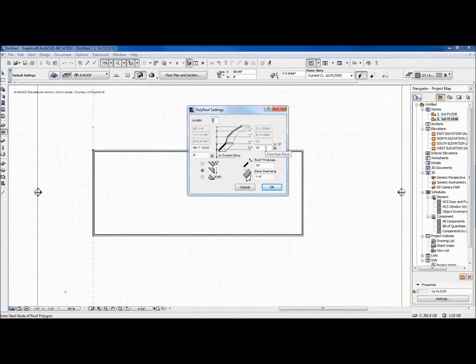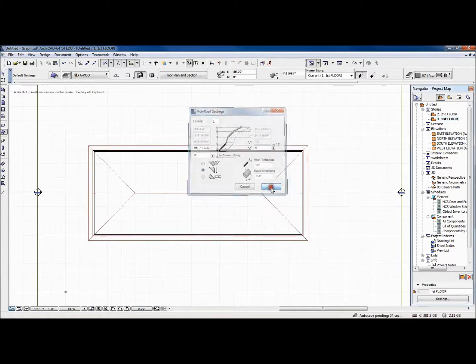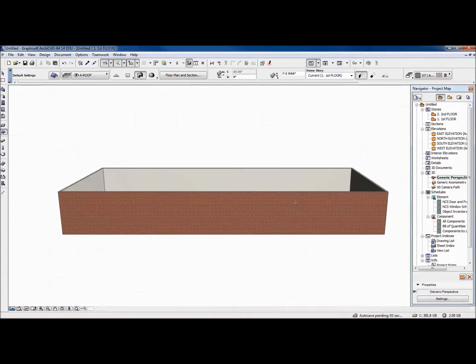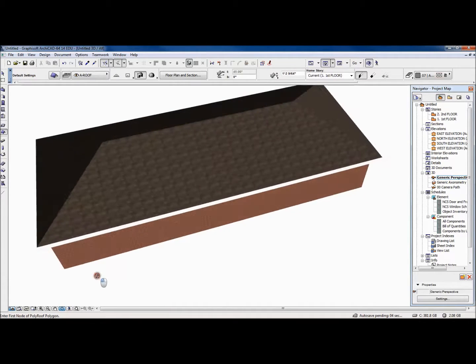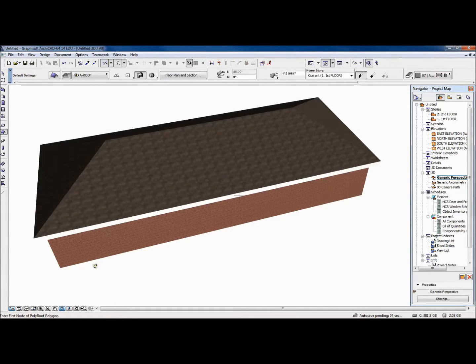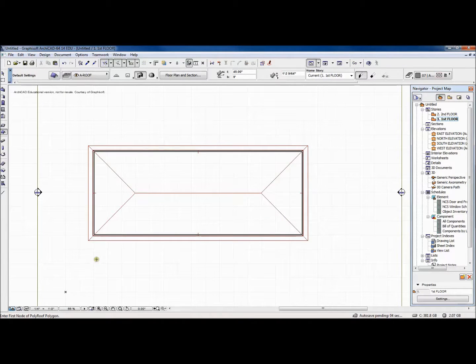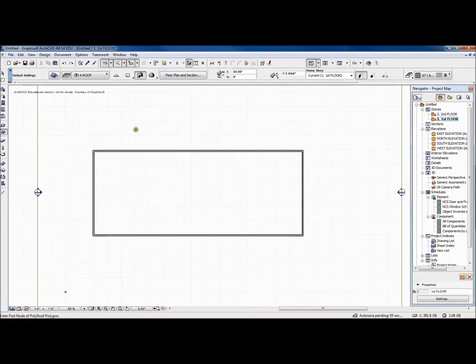Then it will ask a couple of questions. First of all, what is the pitch? And we can set the pitch maybe at a 6/12 pitch, or 6 foot in 12 foot. And we can set an overhang. This would be a 16-inch overhang, and that is fine. So we'll click OK. And so I'll tap F3 to see what that looks like. And the roof looks as if it's working pretty nicely. And so that's a really easy tool to use. I will go back to F3 or F2 for the two-dimensional view and Control Z that roof so that it's gone. That one's actually pretty easy.